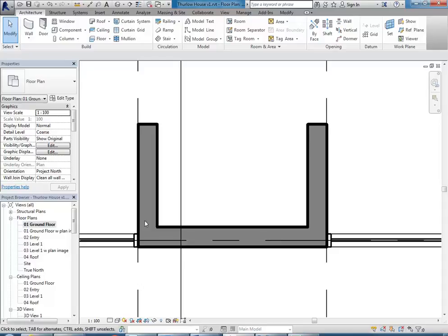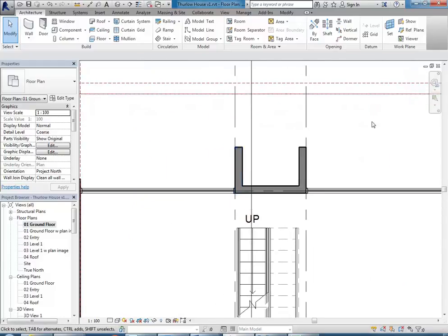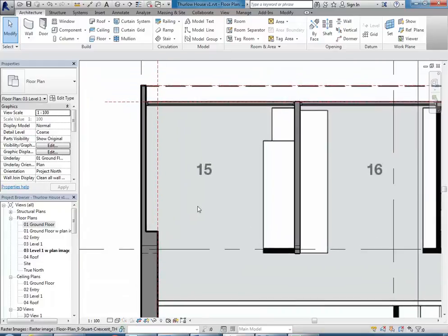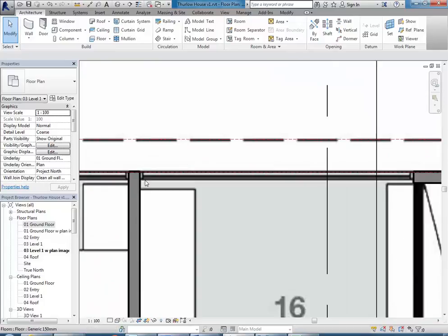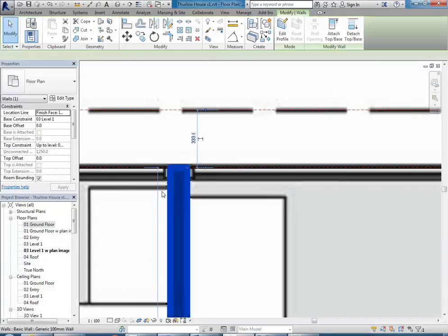You almost don't notice it at first. But imagine if you were drawing that in AutoCAD, you'd have to manually go and fillet those lines together and do all that work to get the wall join. So Revit does that automatically, but here we don't want it to do that, because if it joins the walls automatically, we're going to have a problem when the curtain wall goes in there. So you've got this, like I said, almost hidden option.